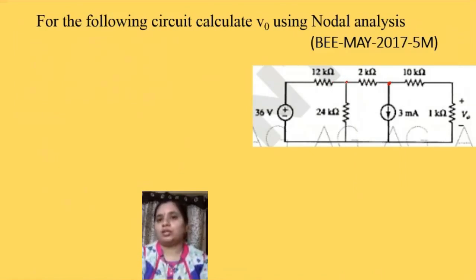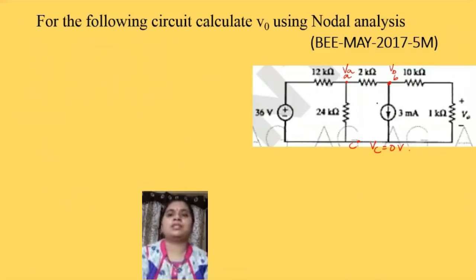Here the three points meet, so it is A, and again here, so it is B. This is VA and this is VB, and as this is common for all, you can take it as point C, but the value of VC is 0 volts. We can first split the given circuit into two parts, and then solve using the equations.